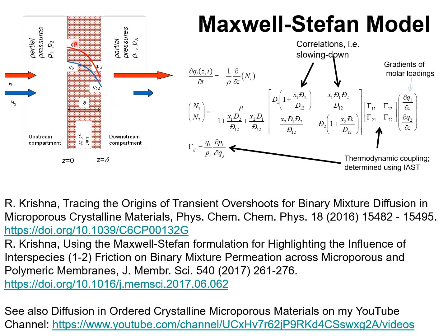The molar loadings q1 and q2 at the upstream face, q1δ and q2δ at the downstream face can be determined from the mixture adsorption equilibrium. Typically, we use the ideal adsorbed solution theory to determine the component loadings in the upstream phase and the downstream phase of the membrane layer.